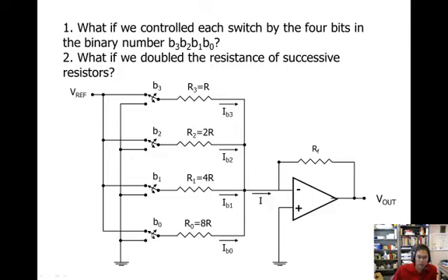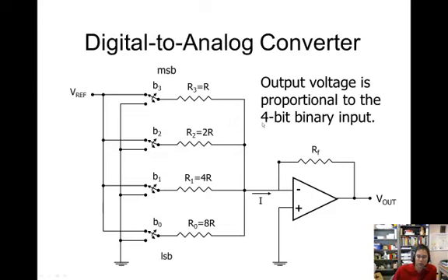And these switches here, we can think of them as being controlled digitally. So our N-bit digital vector will determine whether or not these switches are closed or open. And so if this is 1, 1, 1, 1, then all of these switches are on. All of these resistances will add up. And so that's exactly what a digital to analog converter is. Pretty simple circuit.